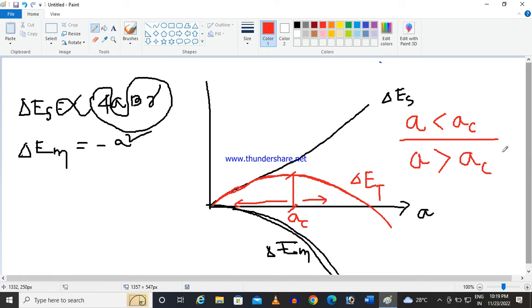Okay, so this condition is called leak before break. Breaking will not take place. It will leak. At most, it will leak. We can take some preventive action to do that. But if the crack length is greater than the critical size, then it will break, and entire inside whatever the liquid or the hazardous fluid, it will come out.